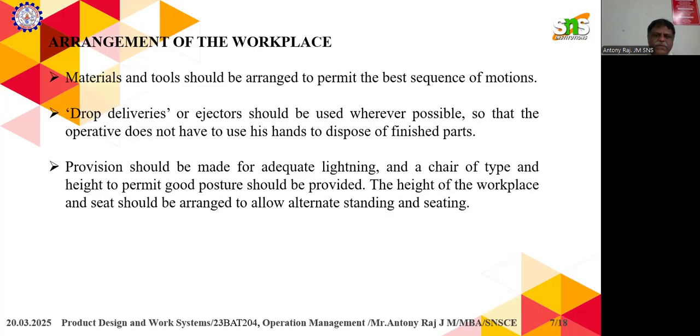Materials and tools should be arranged to permit the best sequence of operations. Drop deliveries or ejectors should be used wherever possible so that the operator does not have to use his hands to dispose of finished products.